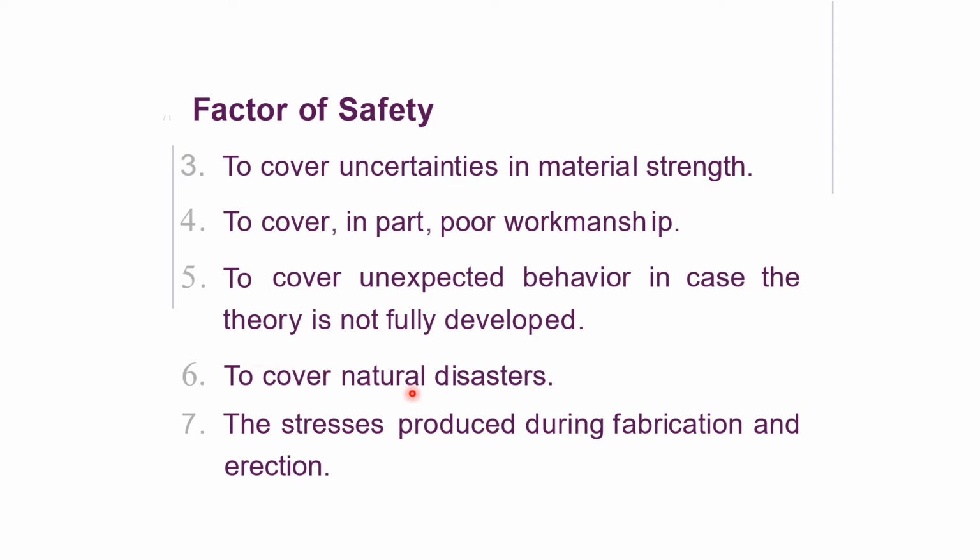The sixth, to cover natural disasters. For example, when you design the building, there is no heavy wind, no earthquake, but when you provide the factor of safety, then your structure can survive under these conditions like heavy wind. The seventh, the stress produced during fabrication and erection. For example, during the construction of a steel building or any steel structure, there are heavy stresses like due to hammering, due to riveting. So all these stresses are also covered with the factor of safety.